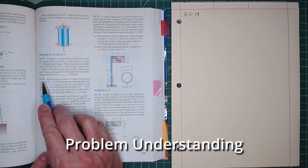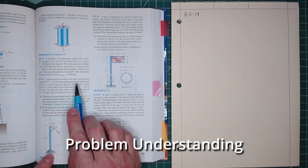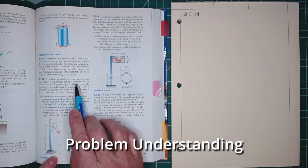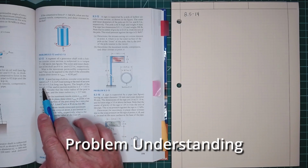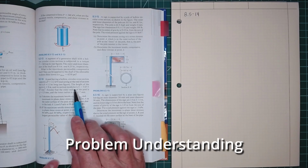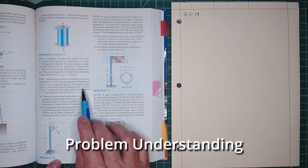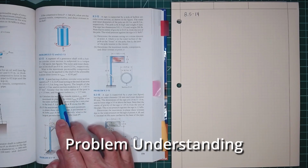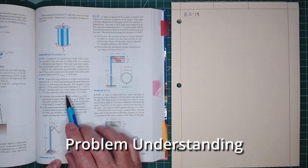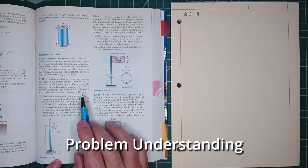So 8.5-14 says a post having a hollow circular cross section supports a load acting at the end of an arm that is 1.5 meters long. The height of the post is 9 meters. The section modulus is given for the cross section of that. Assume the outer radius of the post is 123 millimeters. The inner radius is 117 millimeters.